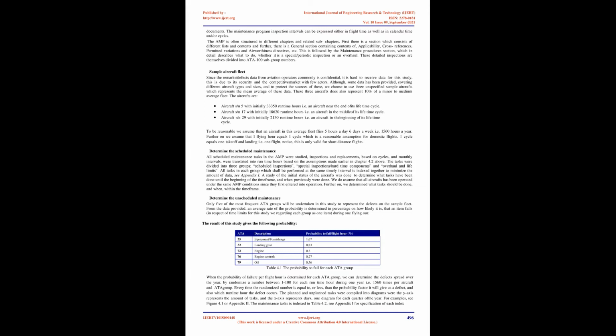The AMP is based on several publications and documents, such as Aircraft and Engine Manufacturer Maintenance Manual, Airplane Flight Manual, Parts Catalogs, Service Bulletins, Airworthiness Directives and other state authority regulations. A list of the latest revision must be kept by the operator's technical department. The operator is responsible for the technical documents.